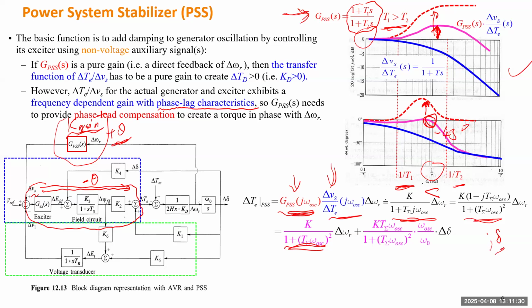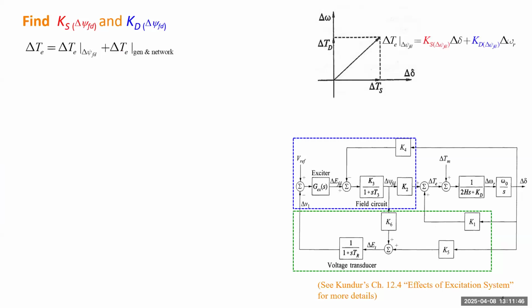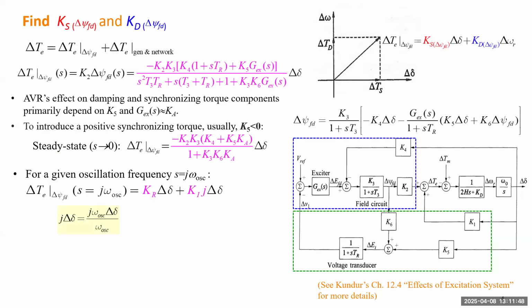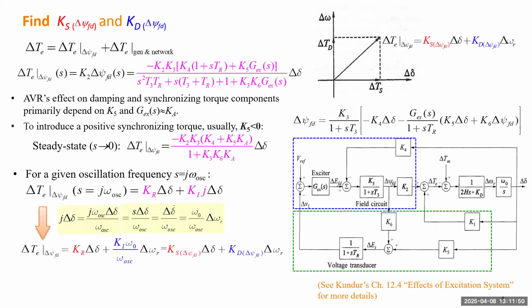Whenever you see J multiplied by delta, this can also always be translated to something related to delta omega, which is here. So if you forget that formula we proved, whenever you see J multiplied by delta, delta can always be translated by this one. So you'll create a damping component.